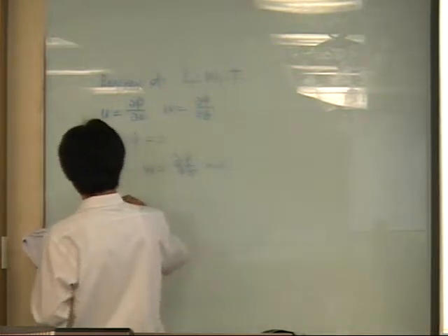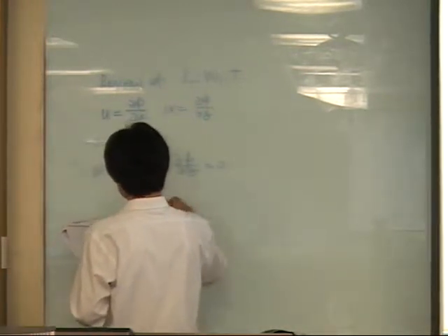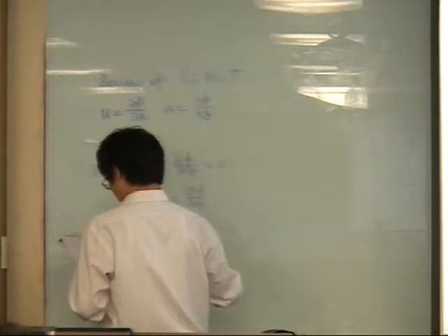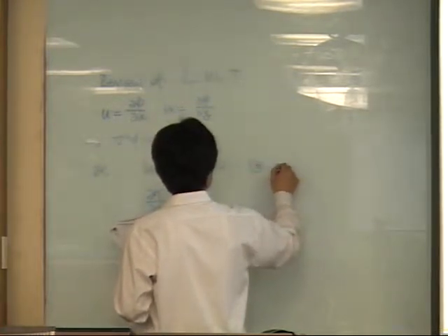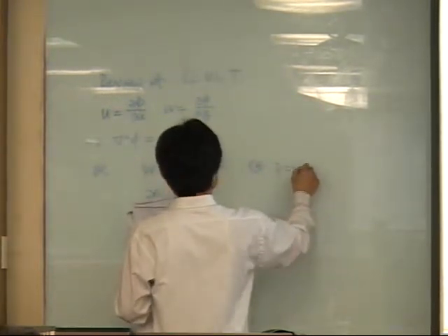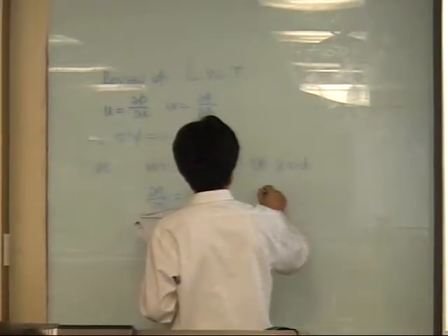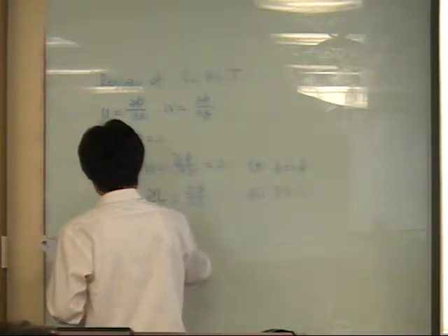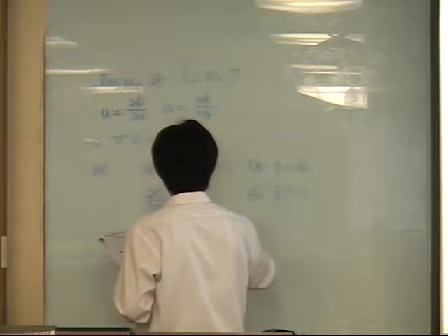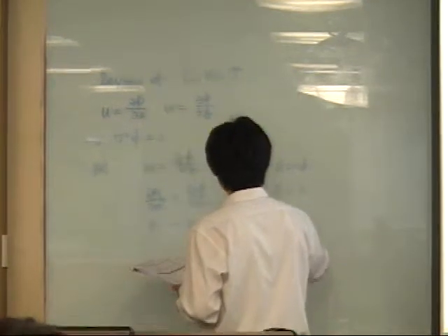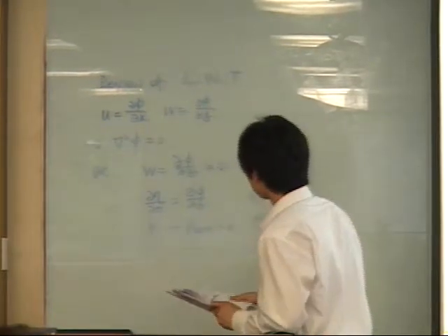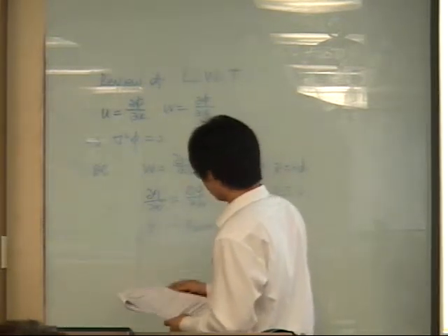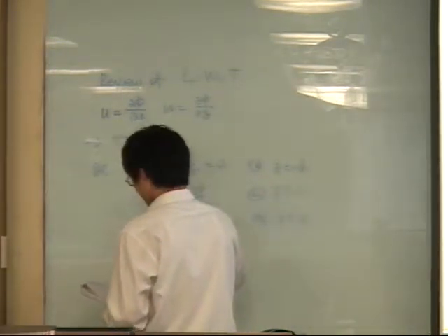On the free surface, the kinematic boundary condition, I'll just write it down, and this is at z equals minus d. Based on that notation, this is at z approximately 0, and this pressure is 0. This is the dynamic boundary condition. Okay, that's it. So from here we can do some further work based on Bernoulli's equation.